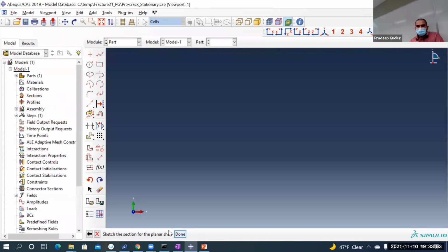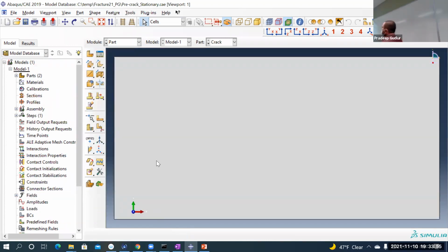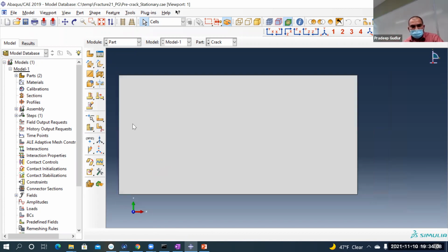And say done. So you just created a surface that you can call a crack. Somewhere down, when you enter the XFEM information, we're going to call this a crack. So that's all the parts that we need.